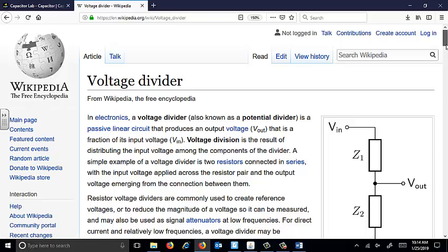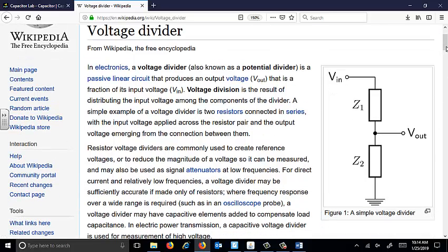So that's what it looks like. We had our 5 volts in, we had ground. We were measuring the voltage between the two resistors. This would have been the variable resistor, and this would be the fixed resistor. They're using Z's there not because they're falling asleep, but because Z is a symbol used for what's called impedance, as we'll find out later. And resistance is part of impedance.